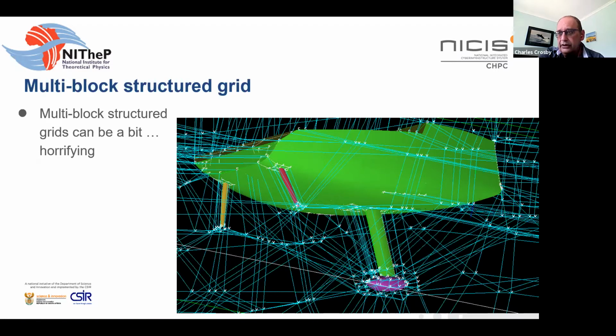And we know of ways that give you good quality grids around airfoils, and they involve a lot of grid cells to get a nice wrap of the grid around the geometry. Also, because it's floating on water, you'd like to be able to have your grid near the water surface more or less parallel to the water surface and refined in that region. Small dimensions in the vertical direction. So you've got quite a lot of complexity that you want to handle.